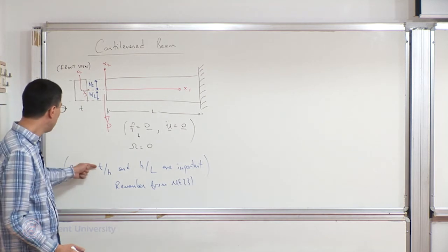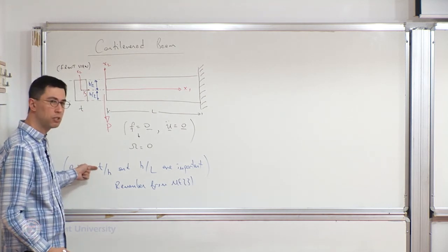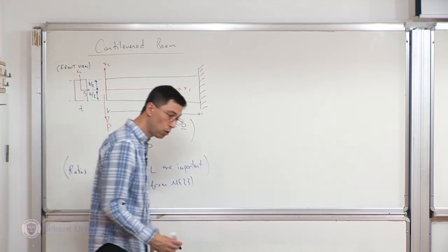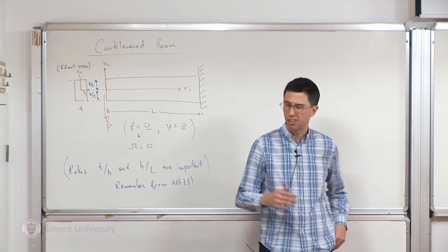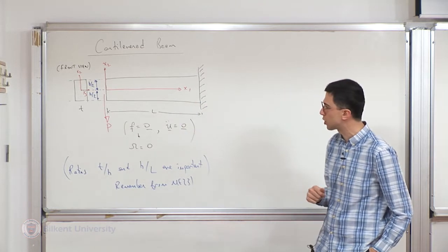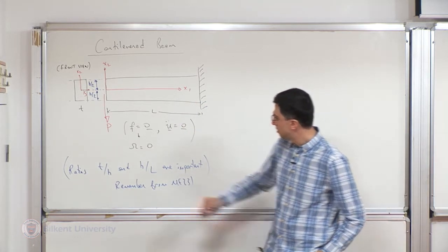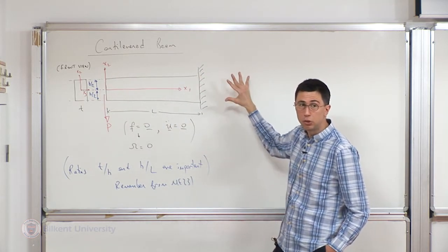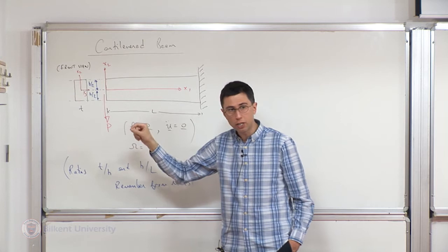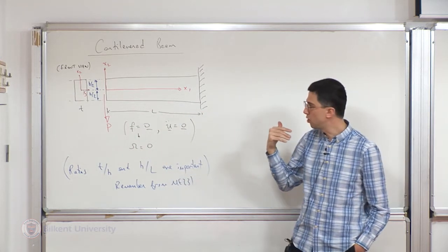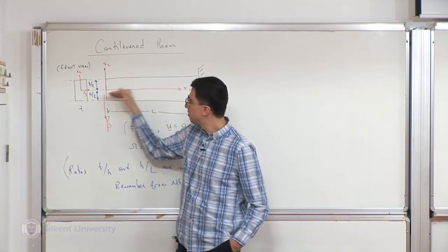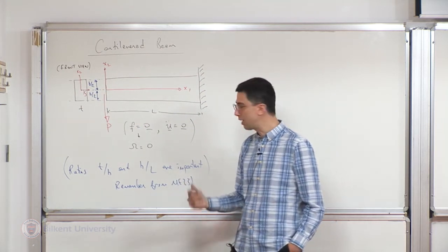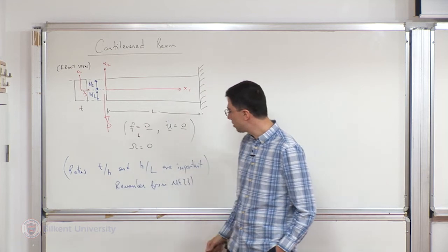For instance, the thickness dimension is important because in general, if it's not ideal plane stress or plane strain, there will be variations along the thickness direction. But our approach in an intrinsically 2D setting assumes only ideal plane stress or strain. And in those cases, the thickness dimension, the x3 dimension, is not important. If those are not ideally satisfied, this ratio is important.